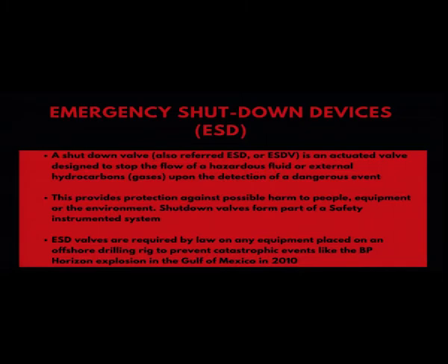Emergency shutdown systems also have PLCs, but they are very specifically designed on cause and effect. For example, if the compressor knockout drum level goes up, then the liquid will carry along with the compressed gases, which will upset the entire plant in the downstream segment. So based on every cause, there will be multiple effects. For example, if the coil outlet temperature in the furnace goes beyond 370 degrees centigrade, then the crude oil will get coked up in the furnace. It is also going to upset the distillation column. So there are several other effects for a single cause.